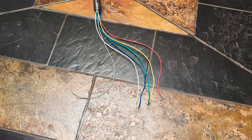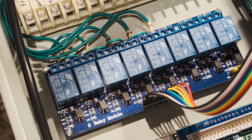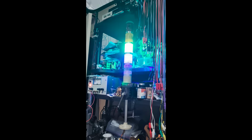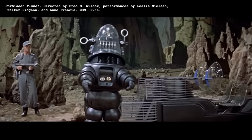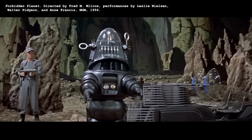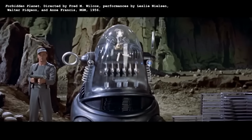Wiring it was very simple. Just connect ground and put 12 volts on the lines for whatever lights you want on. I grabbed an 8-channel relay module for this, which was ridiculously overkill, but I thought the analog clicking of the relays would be a nice sensory touch. Plus I anachronistically imprinted on Forbidden Planet in the 80s, with the weird result that this sound still feels kinda futuristic to me.